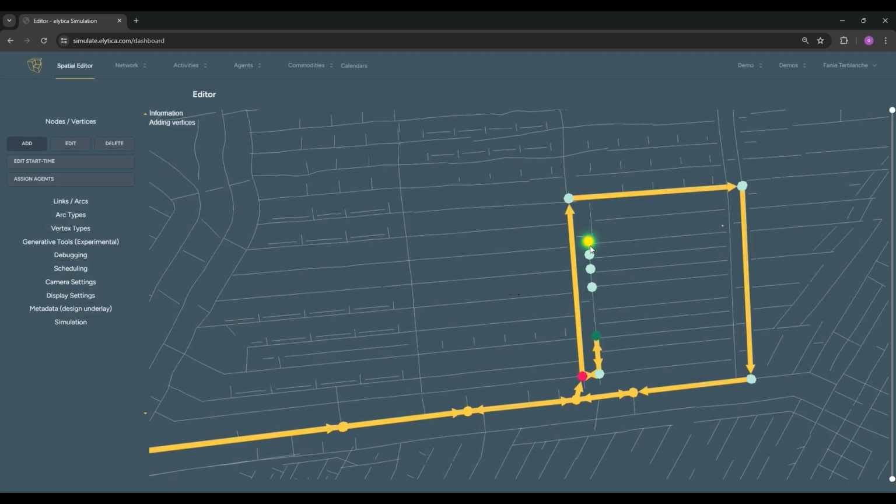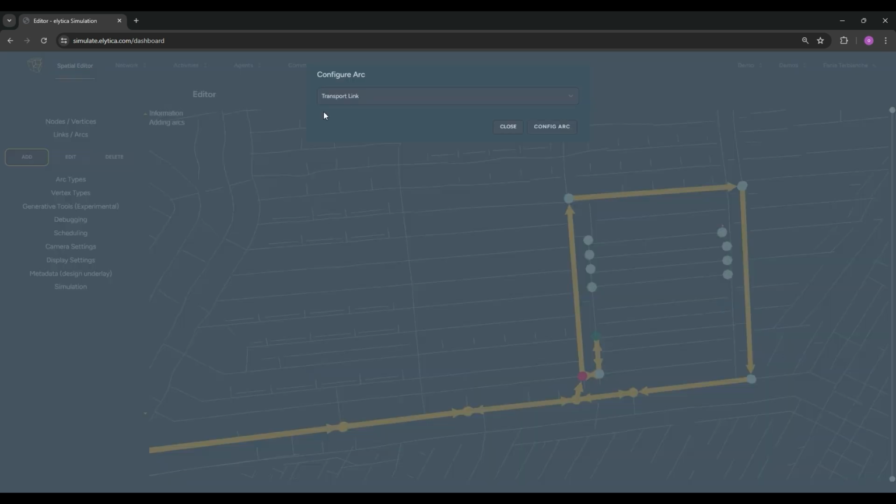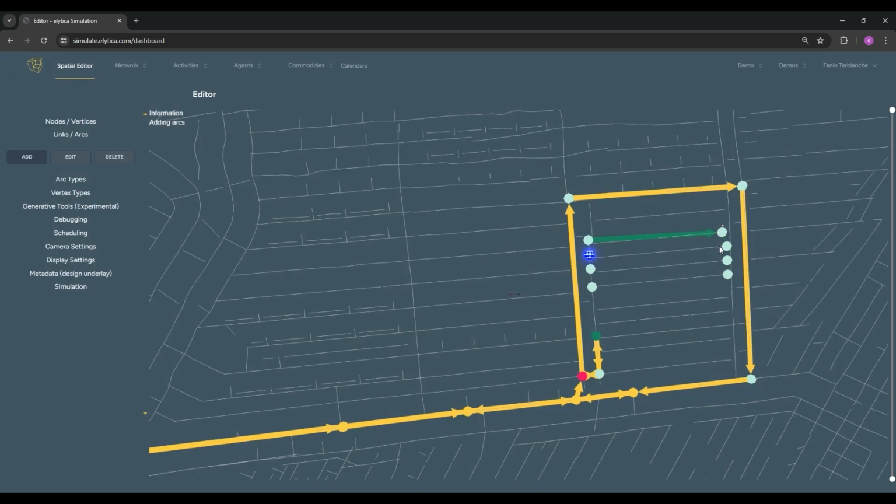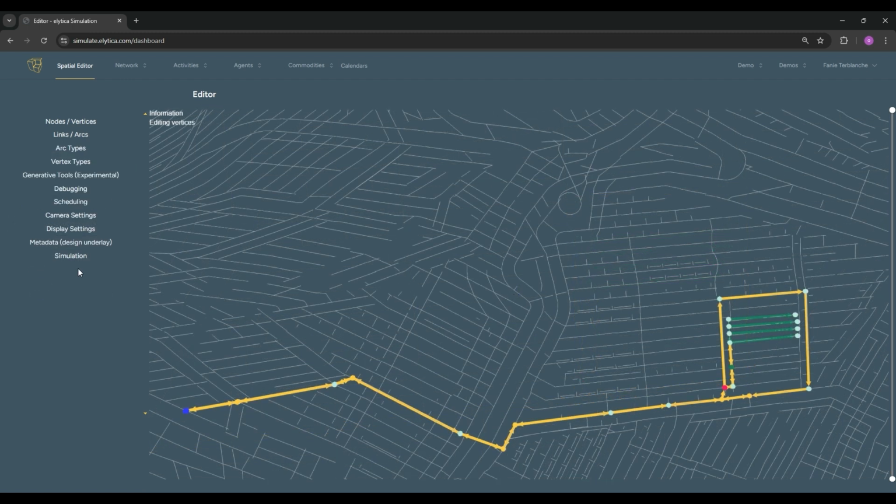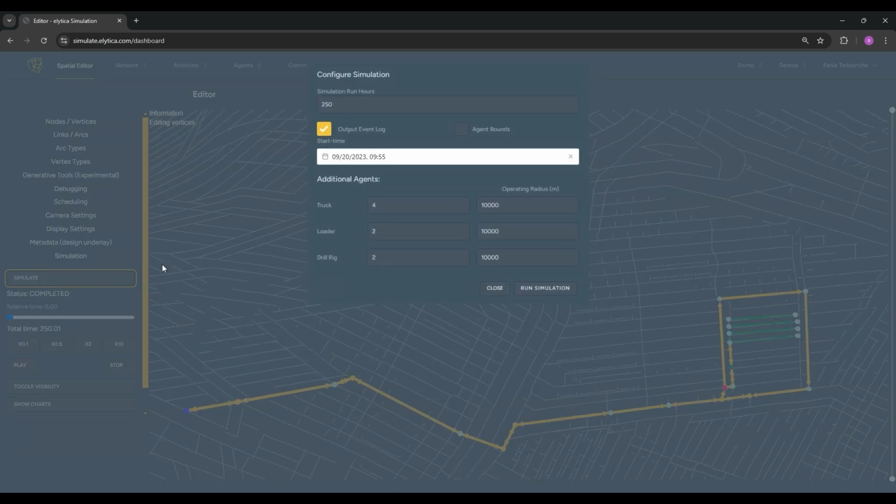development mining cycle activities. To model the continuous repetition of a mining cycle, each green link is divided up into parts that correspond to a sequence of activities such as drilling, blasting, loading, and support installation. The simulation model will now dynamically adjust the source for the loader according to the progress of the development end. For this simulation run, we want to validate a schedule that was based on a fleet size comprising 4 trucks, 2 loaders, and 2 drill rigs.